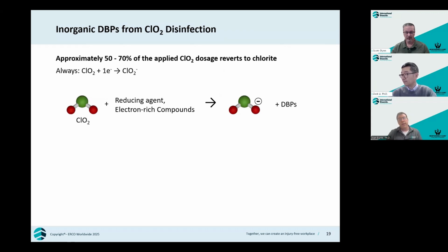We've already discussed how chlorine dioxide helps to minimize the halogenated disinfection byproducts that often arise from chlorine treatments. But the main byproduct that arises from chlorine dioxide treatment is the chlorite ion. When it reacts with electron-rich compounds in the disinfecting step, it is a pure one-electron transfer reaction, so a very pure redox reaction occurs where the oxidized byproducts are generated and chlorate residual also appears.